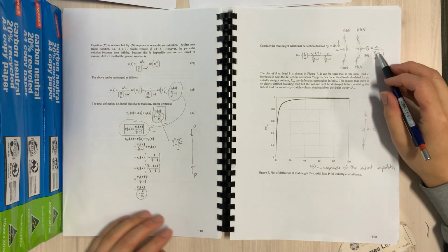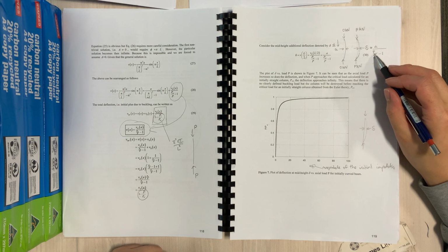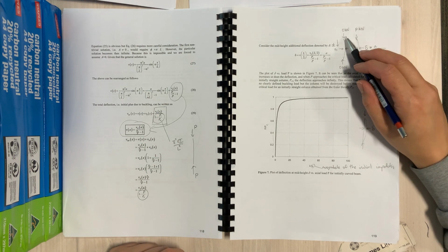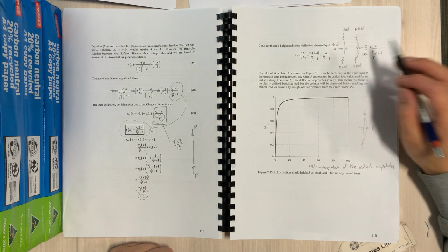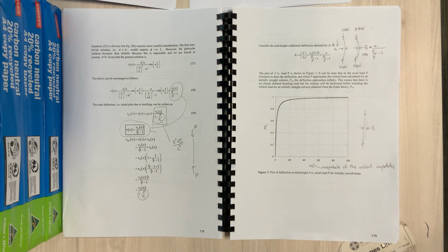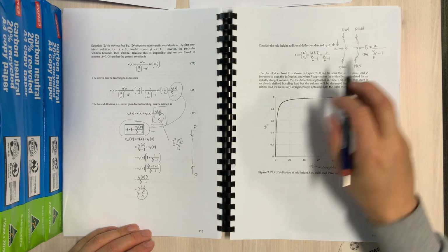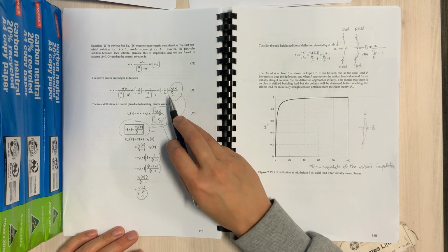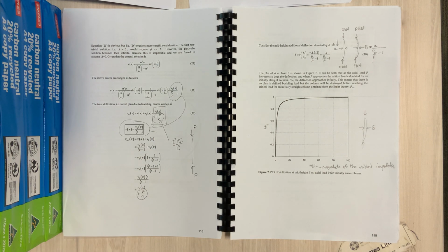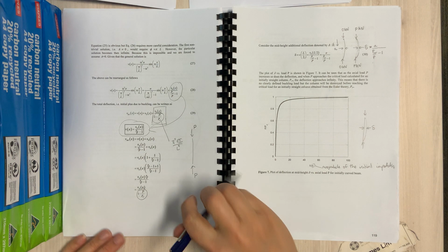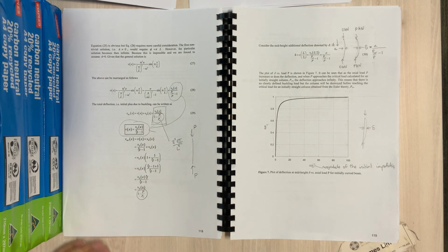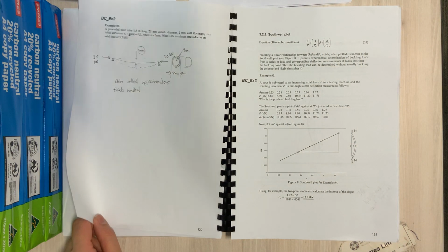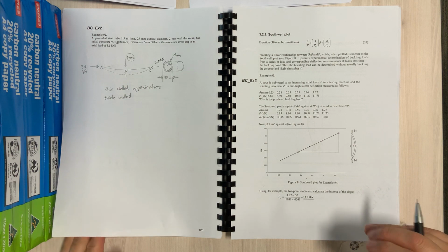So when your P is very small or 0, then that becomes infinity. Infinity minus 1 is infinity. A divided by infinity is 0. So when the load is very small, there's no additional deflection at the center. So that's where that equation comes from. Sometimes I am asked, when you see the PCR over P and you see the P over PCR, whether that's an error or a typo. It's not a typo, and you can work through the derivations if you want to. Anyway, that's equation 30. So now we come on to what's known as the Southwell plot.